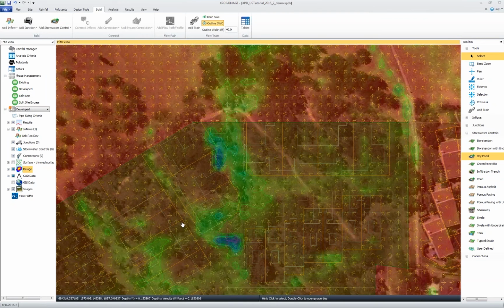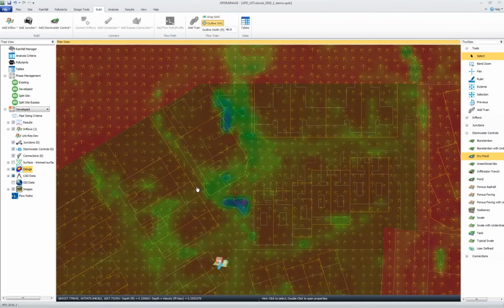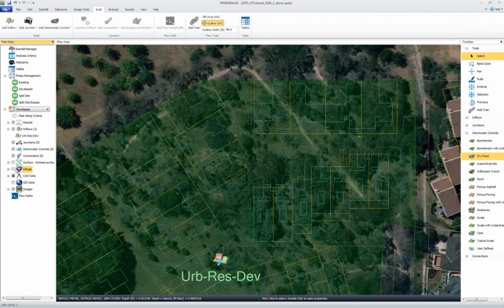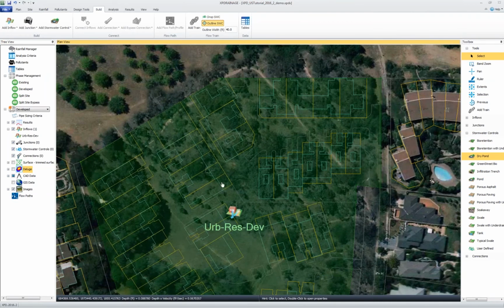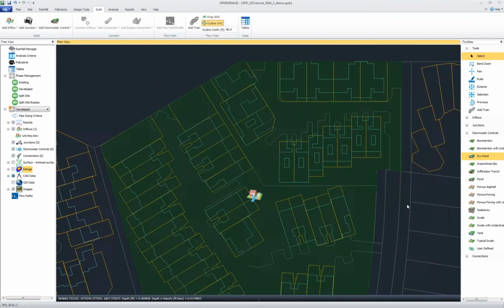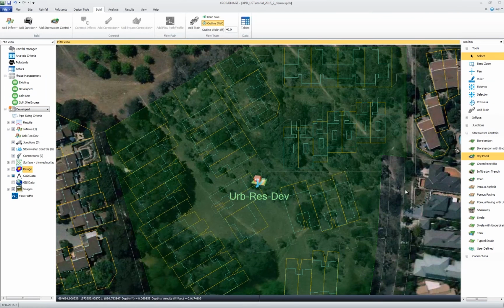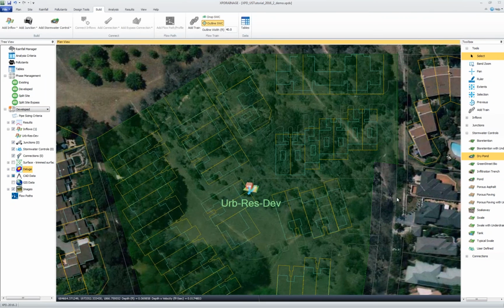One question I saw pop up that I'll talk about right now: what's the input data for the Deluge option? Just a surface. That's all you need. I happen to have a background surface, and you can see as I pan around the lower left corner, it shows the depths, or sorry, the vertical information being picked up from that surface. So if you have a surface, right-click, go on Deluge, and it will apply a little bit of rainfall to that, and you can find out where the flow goes. So it's a planning level tool, but can be really powerful for that 5-minute back of the napkin sketch. Okay.